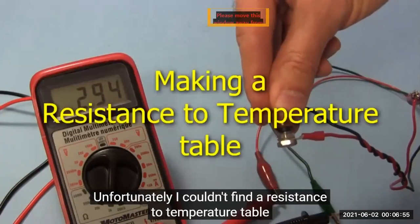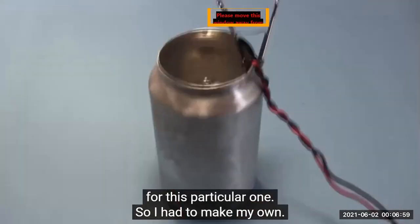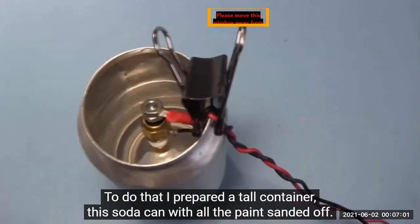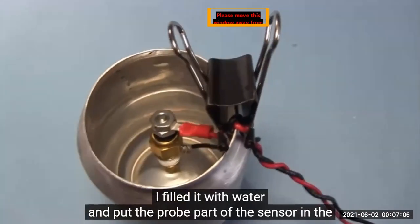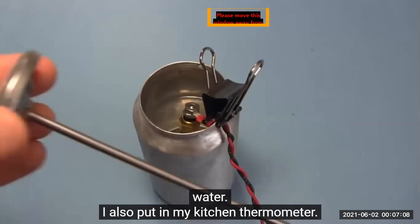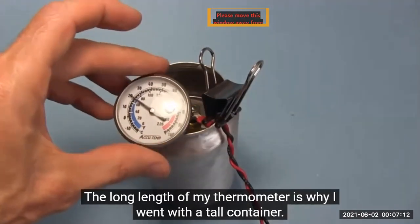Unfortunately, I couldn't find a resistance to temperature table for this particular one, so I had to make my own. To do that, I prepared a tall container, this soda can with all the paint sanded off. I filled it with water and put the probe part of the sensor in the water. I also put in my kitchen thermometer. The long length of my thermometer is why I went with a tall container.